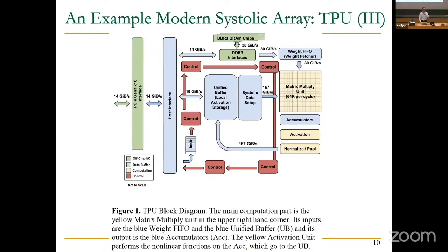Yes. Not necessarily, yeah, not necessarily. So they're probably taking advantage of the reordering internally. As long as you get the right result, it doesn't matter which order you follow. But yeah, if you think about that, in a von Neumann architecture, you have a sequential order dictated by the program, right? You have to obey that order because that's the architecture you have. Here, a lot of things can be happening concurrently. So that's one of the other benefits of systolic architectures. You're not tied to an order.